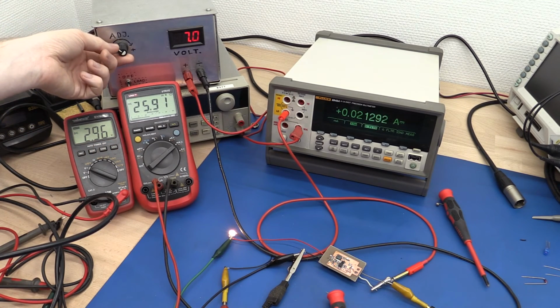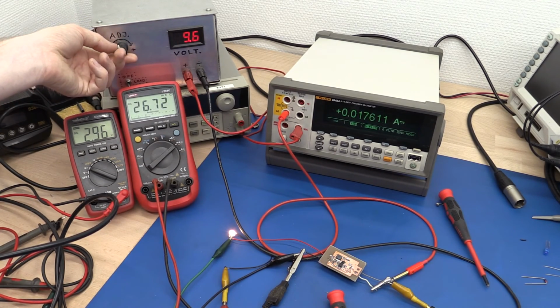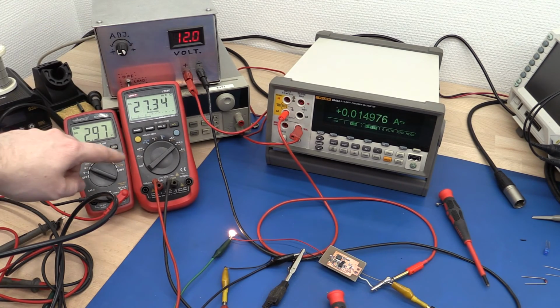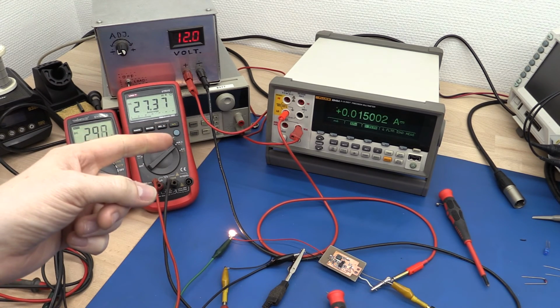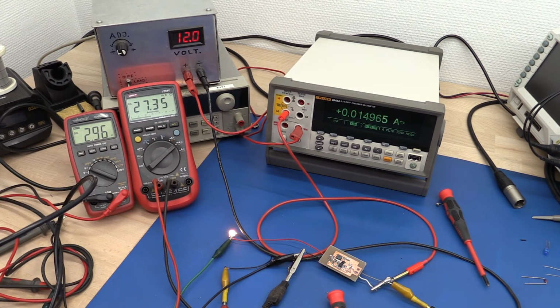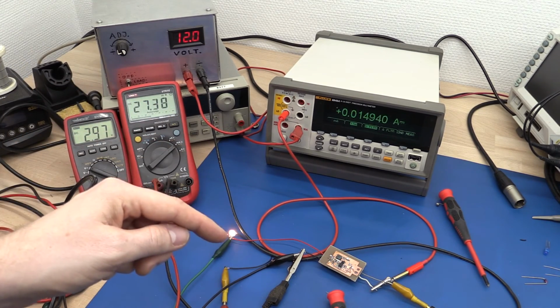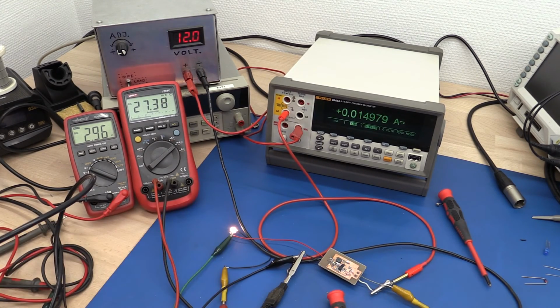If I increase the voltage, we see the input current goes down. Let's choose 12 volts. We see the output current does increase a bit. We didn't really expect that, but I guess it's okay for a small amount. And now we only get an efficiency of 45%. We are running a pretty low current though, well below the examples from the datasheet. And the LED, it's not even warm, so I guess we can increase the current.